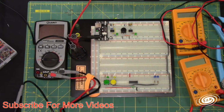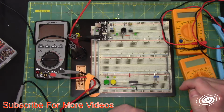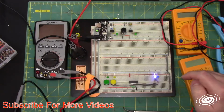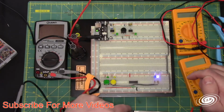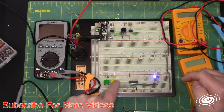So we come back to our chip. Here is our chip. It is a 74LS00. It is a quad 2-input NAND gate. If we turn on the circuit, it is in the set position. If I press the reset button, it will reset. If I press the set button, it will set.